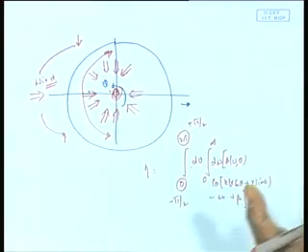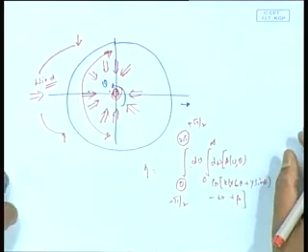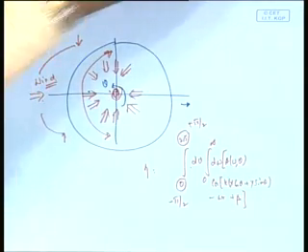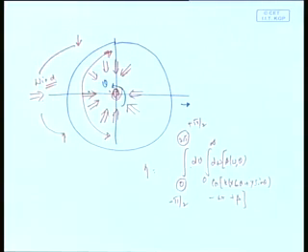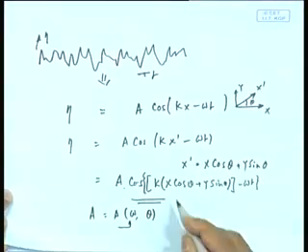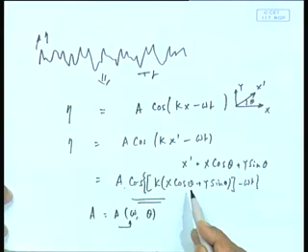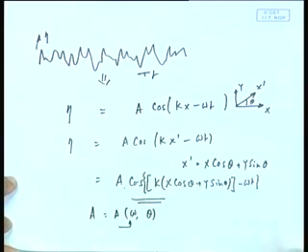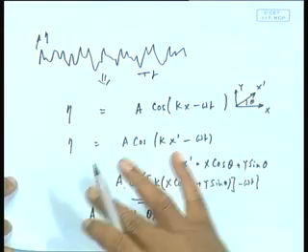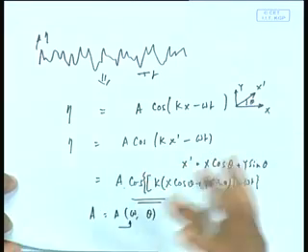So once again, coming back to this irregular wave, I can model this irregular wave by summing waves from all directions. But now I find that I need to take the directions only over half of the full circle, which I can write more easily from minus pi by 2 to plus pi by 2 in an integral sense.